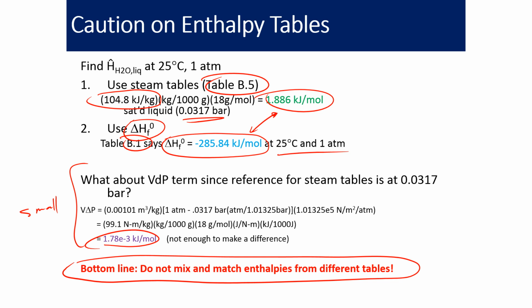One thing to note is that for the steam tables, the reference enthalpy is at the triple point of water, which is 0.01 degrees Celsius and 0.00611 bar.